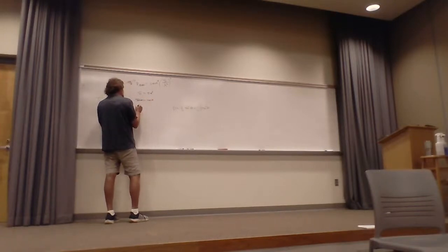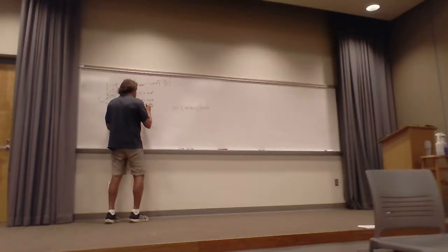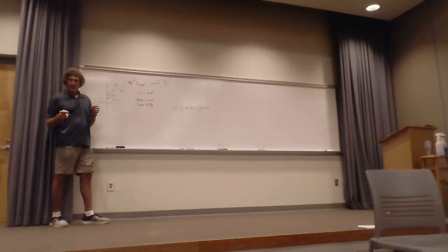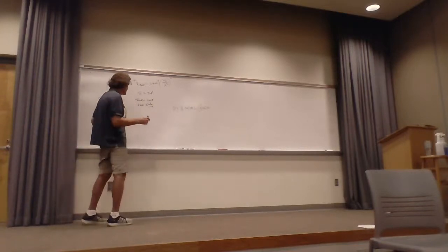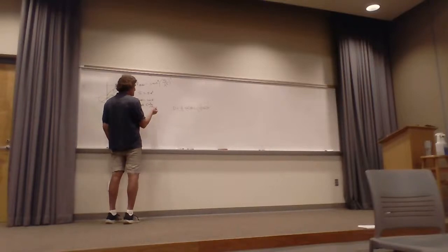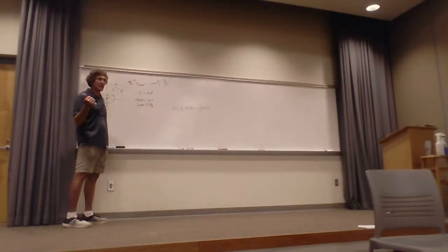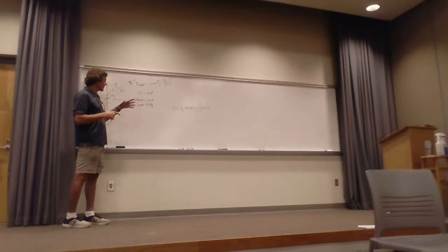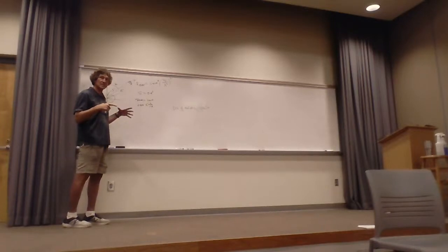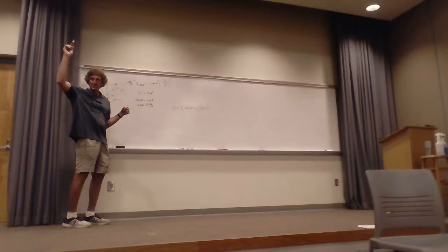I make the case a small loop is when the perimeter 2 pi a is less than lambda over 10. He just says it's small. You take the total length around, straighten it out, and that length has to be less than 1/10 of a wavelength. This is a rule of thumb. If you look at the E fields as the radius gets larger at a given frequency, it's not really abrupt, but there is a noticeable change.